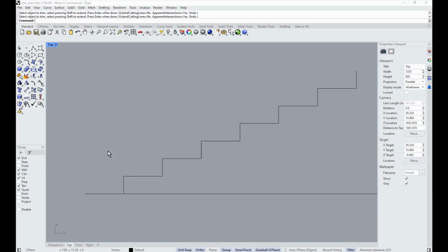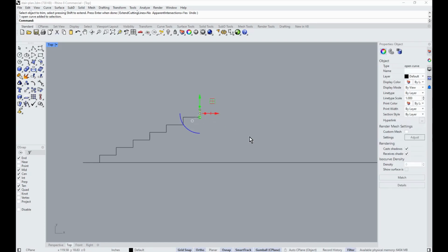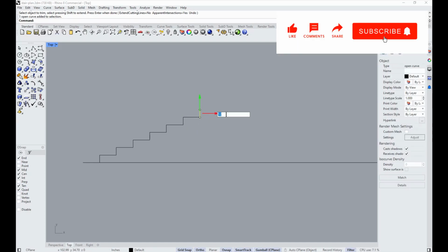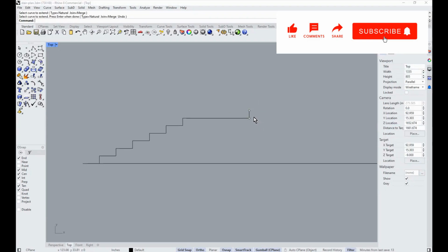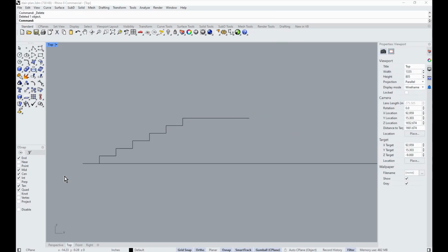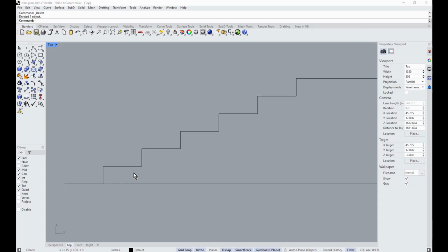So this is recreating the staircase that I had, and let's see here, 1, 2, 3, 4, 5, 6. So I'm going to move this over another 36 inches, extend. There we go. So that's showing kind of like a landing right there. So I have a section of like 6 treads and then a landing. I make a turn just because of how this particular house laid out. But one word of wisdom is when you go shallow like this for a comfortable staircase, it's going to be difficult to make the treads out of a 2x12. Usually you want to go to plywood and just rip it into 12-inch pieces.